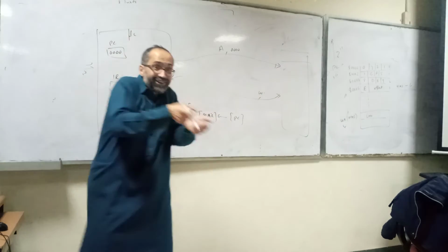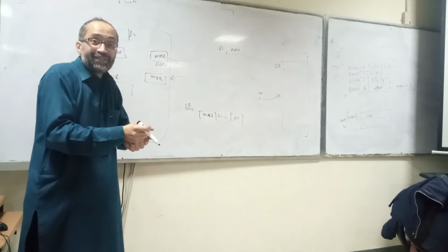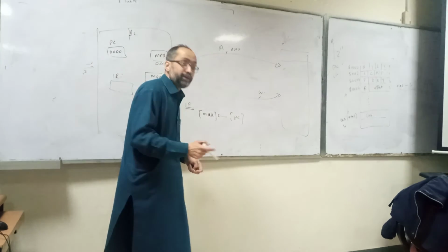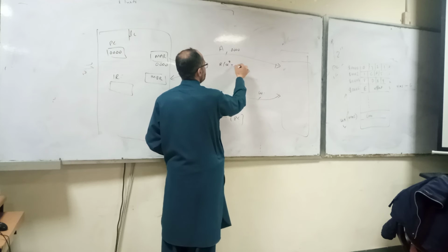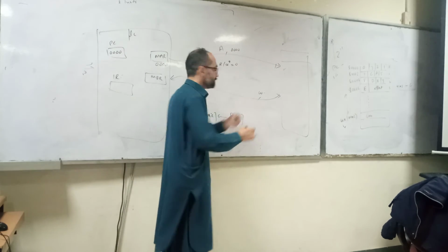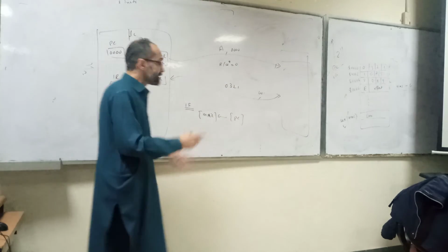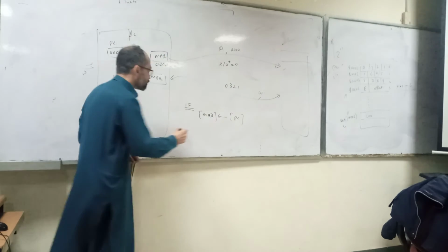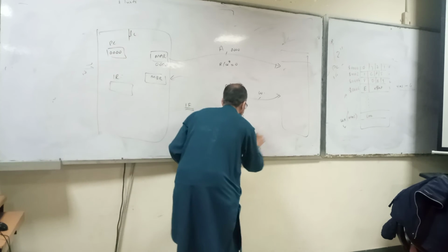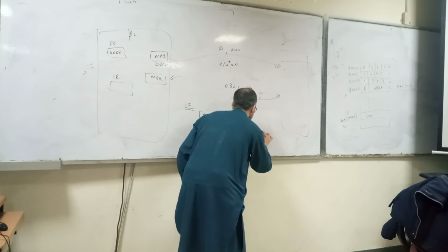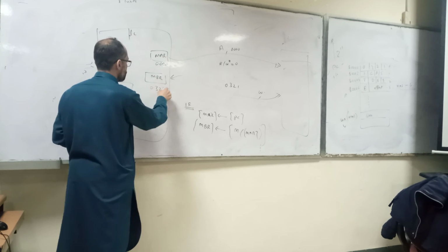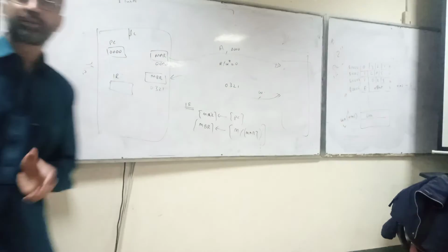Instruction fetch: you want to fetch the instruction at address 0000. Now is it a read operation or a write operation? Read operation, so read bar is 0. Which value will move on the data lines? 0321. This 0321 will go into MBR. So the contents of MBR will be updated with the contents of the memory pointed to by MAR, that is 0321. Now the first stage is done, that is the instruction fetch stage.